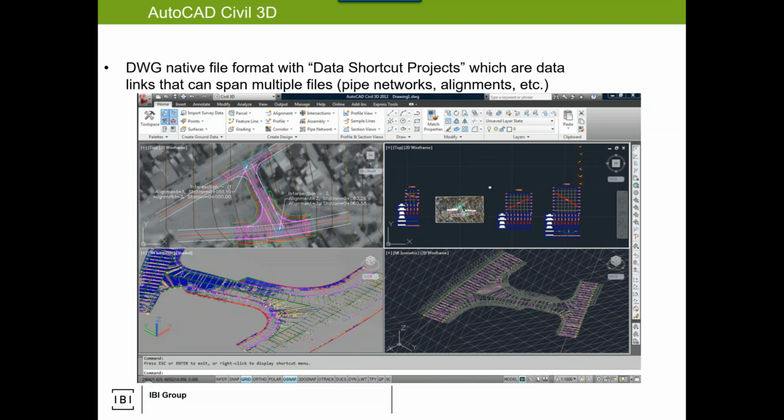So if I'm pipe network 1 and you're pipe network 2, the components are assigned accordingly. If we have 2 different systems named the same because we're not connected via the data, we have chaos, quantities don't work, other elements won't work, and if we're trying to identify systems for clashes, that can't work, and it would just be chaotic. So very fundamental, and I stress this because when we get to the collaboration next week,